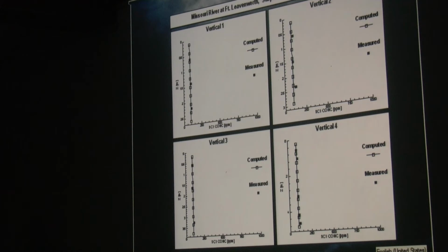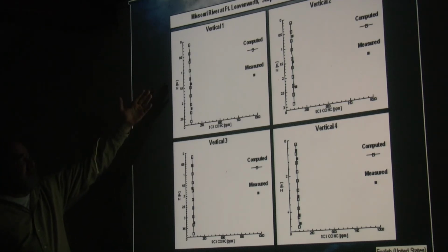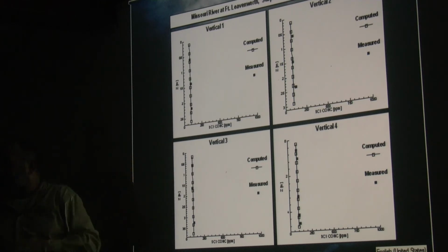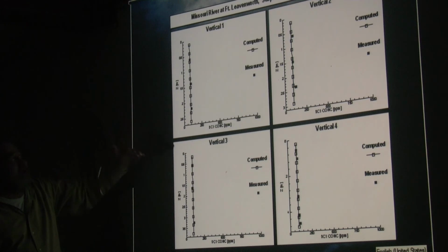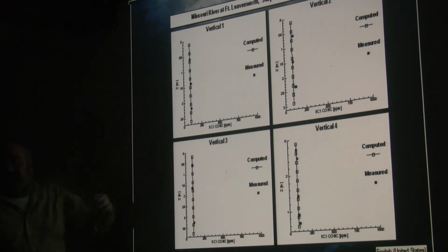And the same thing will be done for suspended sediment. This is an example from the same area, same project. This is one range. In that case, the range had 4 verticals. For sediment, we have 5 verticals typically. And this is a comparison by size class. In this case, we had size class 1, which was very fine, like what we typically have in suspension here.